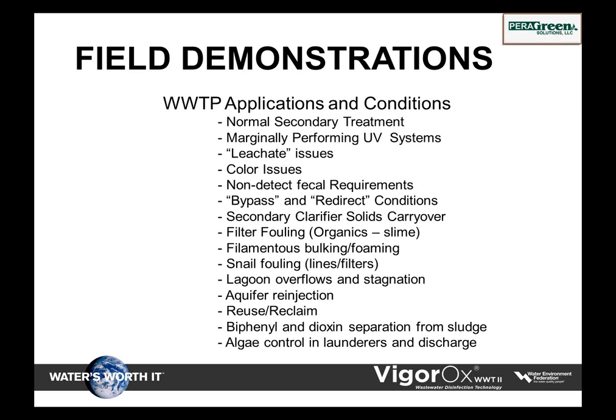But then also, are there reducing agents that may be in the water? Is there a background issue? Are there solids? Do you have solids carryover? Is there a lot of iron that comes in? Are you a high manganese area? Those are key factors in determining what your dosage of PAA will be.